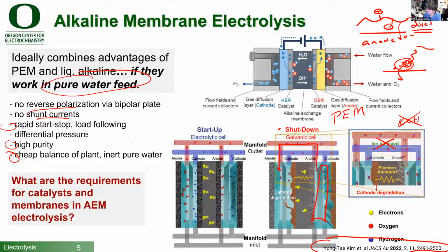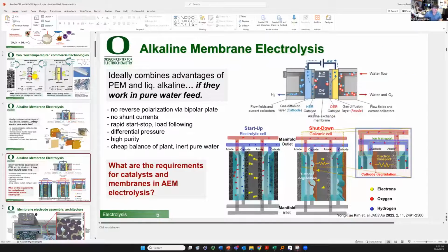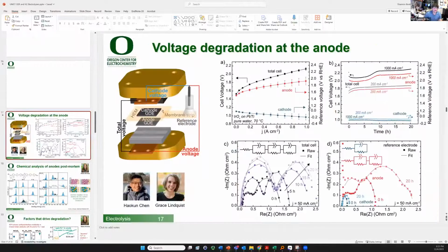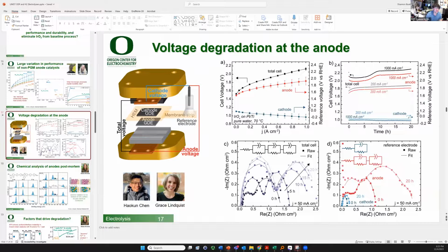What happens if we directly extend the MEA to contact with liquid KOH instead of adding the sense strip to AM? This is about the electrolyzer membrane sensing reference electrode approach. The question is, why do you necessarily need to use a strip? Why can't you just make the whole piece of membrane bigger, I think, right? And we can do that. That works too. And then you put this on here.